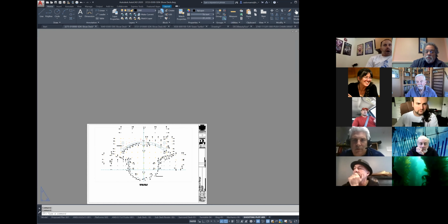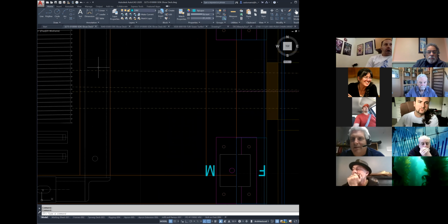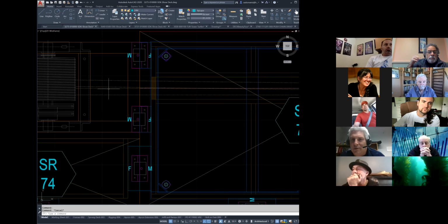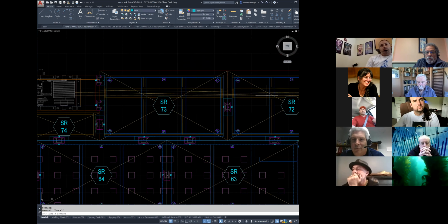Yeah. So this is a kind of classic example of one of those winches, and we need a fair amount of distance to keep that fleet problem resolved. But also you can see we spend time actually drawing that cable's going to move from here to the other end, so that you can look at how wide this kind of runoff track needs to be in order to accommodate the fact that that cable's moving through that path. So it is something to think about.